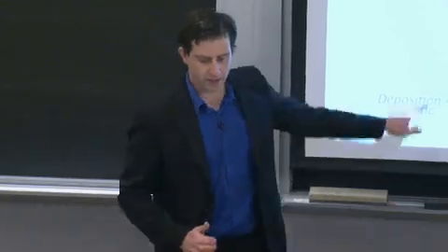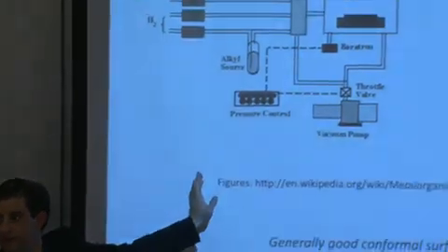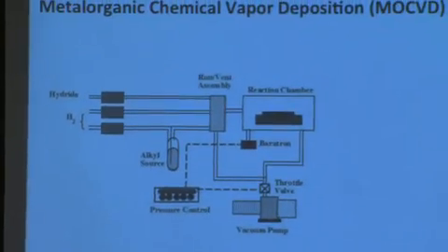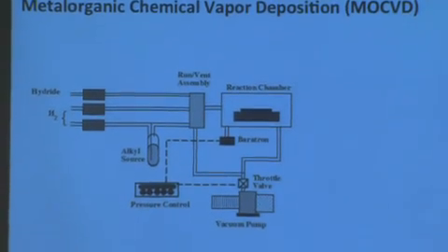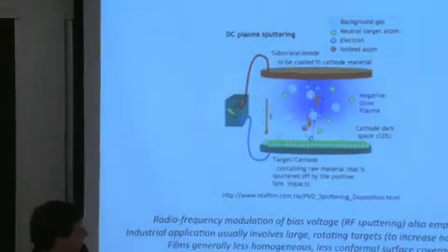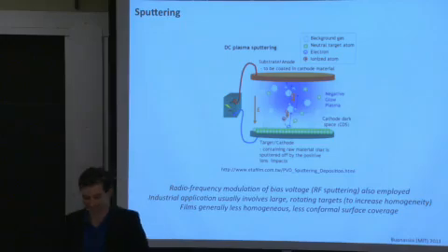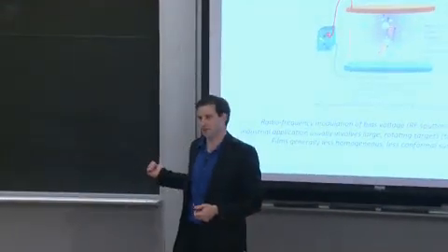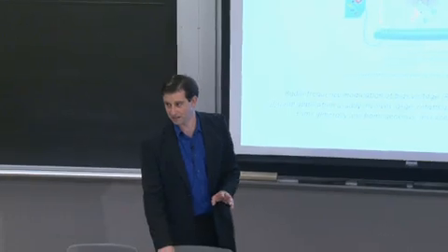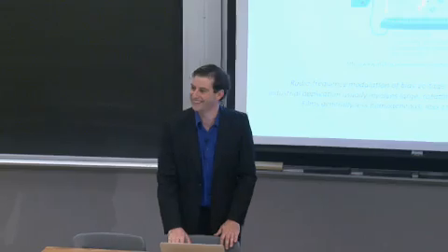So from an MOCVD point of view, you could do a distillation process and increase the purity of your precursor gas and avoid that. So I think two big reasons why MOCVD can produce higher purity films than a sputtered system. One is the quality of the target. And the other, I think bigger parameter, at least in our growth systems, is cross-contamination. And whenever you deposit, say at EML, they have a sputtering system there from AJA, or over at Harvard CNS, there's another AJA sputtering system there, you're going to get cross-contamination. Just look through the logbook and see what people have tried to deposit. It gets kind of scary.